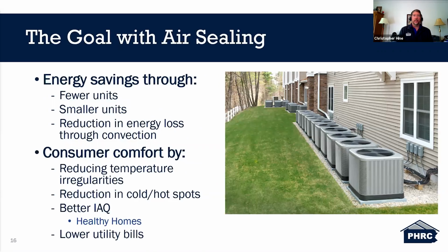So the goal of air sealing is energy savings through fewer units, smaller units, right? The solution is not more bilge pumps. The solution is not a larger bilge pump. The solution is to seal it, you know, to work with what we currently have, or even reduce it. So we want to have fewer units. We want to have smaller units, and the reduction in energy loss through convection, right? If we're going to condition that air, we want to keep that paid-for and conditioned air inside of the conditioned space. We don't want that leaking out.